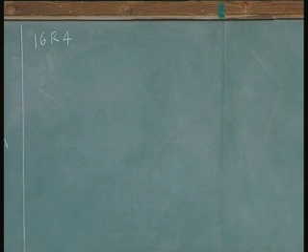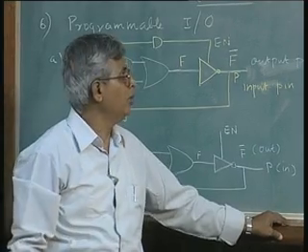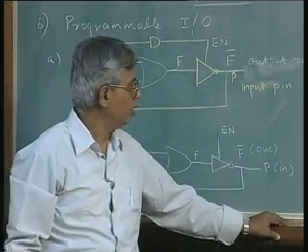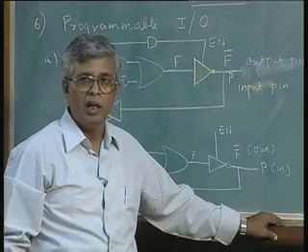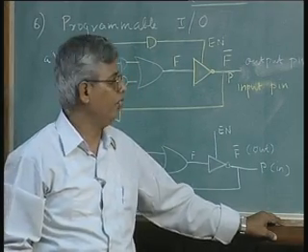I can give you the type number, the part number as they call it, like the 741 op amp, which all of you know is an operational amplifier, but 741s can be made by different manufacturers. Similarly, 16R4 is a generic programmable logic device or PAL, which is manufactured by many vendors.